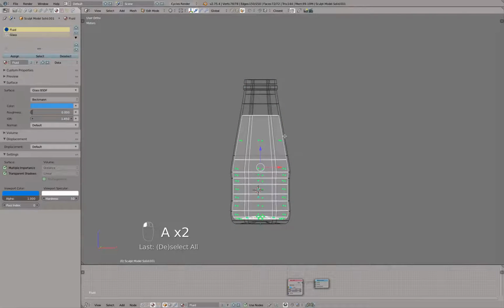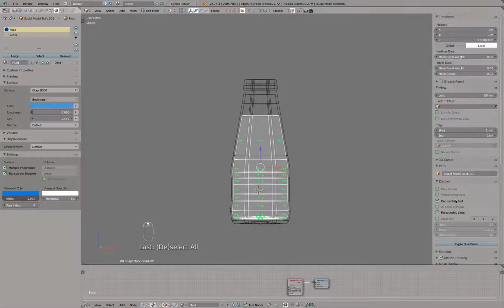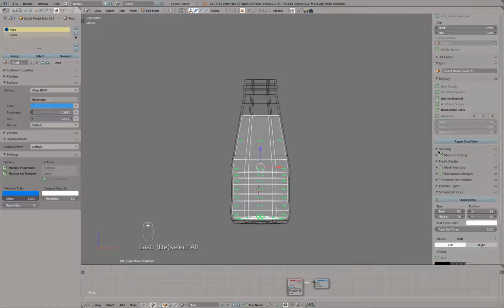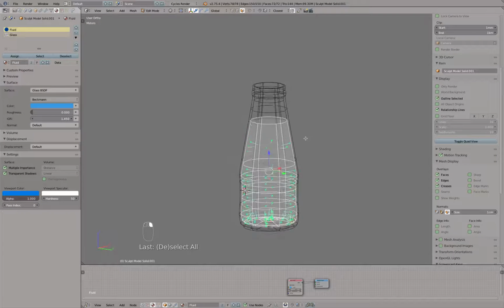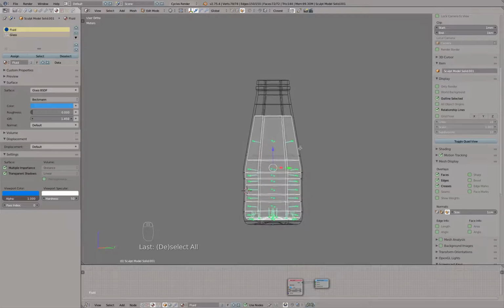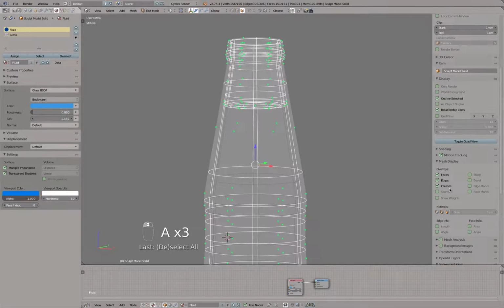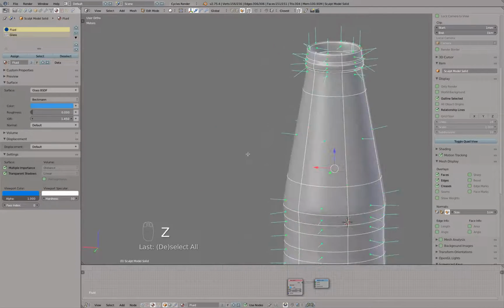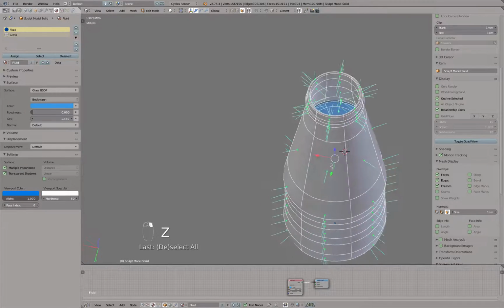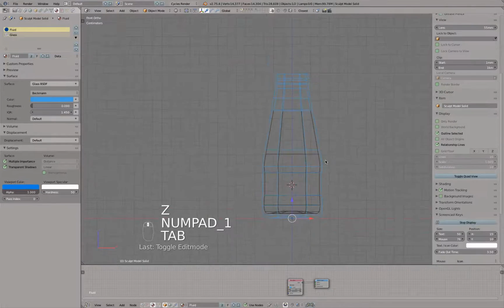One last step, we have to check to see if all the normals are correct. So if the surface looks into the correct direction, and we have mesh display normal 1 centimeter, and you see all these lines actually face to the inside. That is all correct. Let's go to here, and they all face also to the outside. Okay, so this is also all correct.